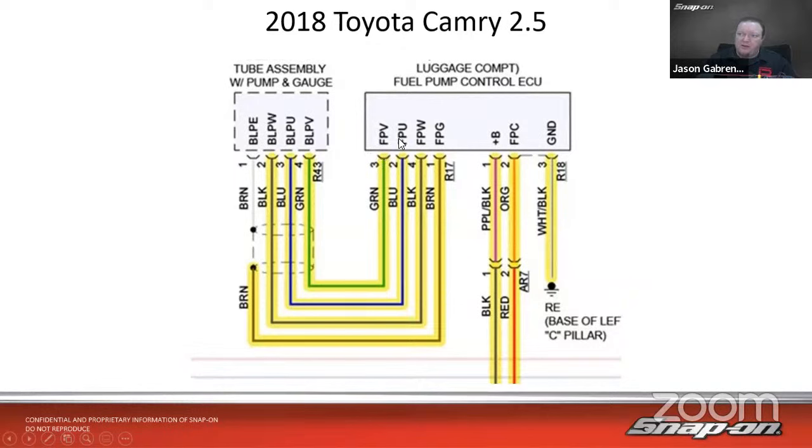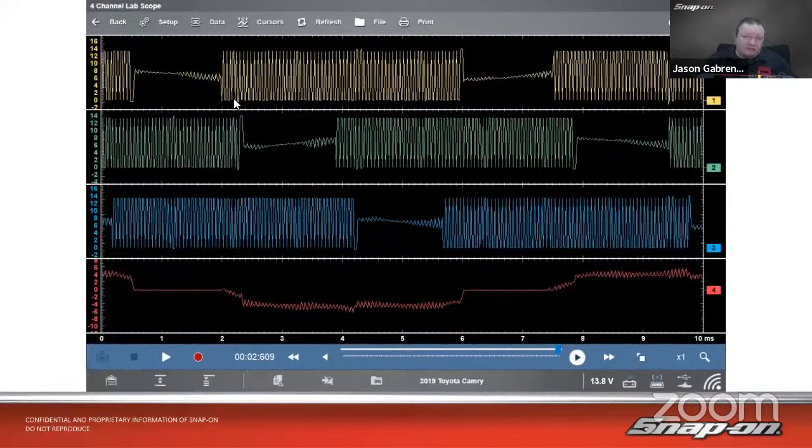And we have what we call V, U, and W. Those are the three pairs of coils, and then the ground there as well. We need to be able to see that, so in this case, we would need to see 3 channels at a time. We can see we have a positive side and a negative side. When polarity goes up, we see an up, and when polarity goes down, we see it down. That's just 2 times through: positive polarity, negative polarity, positive polarity, negative polarity.